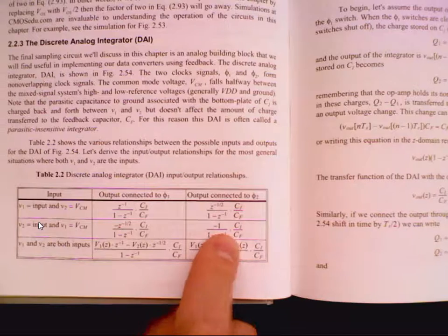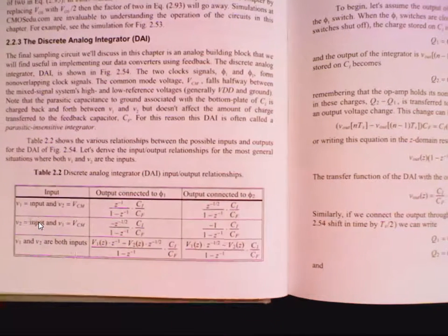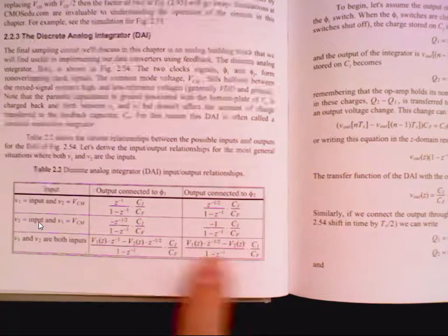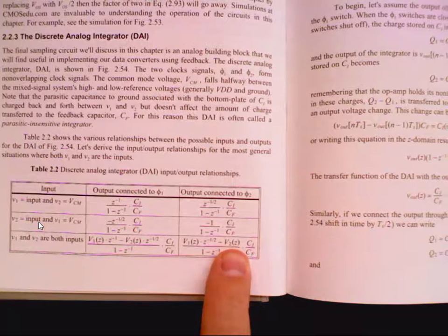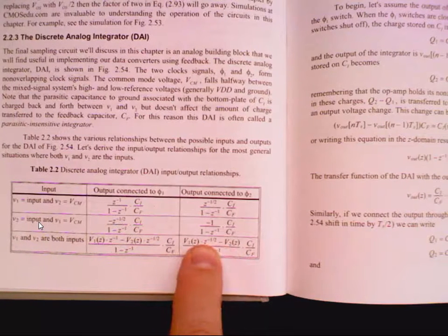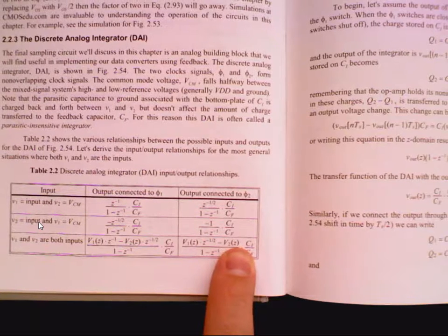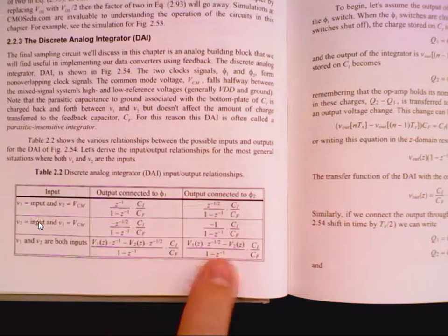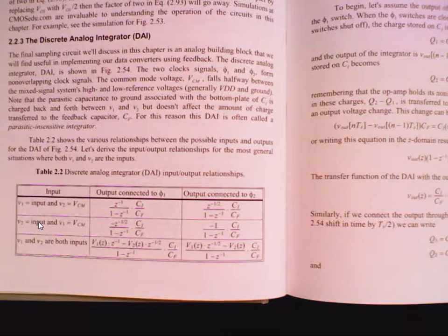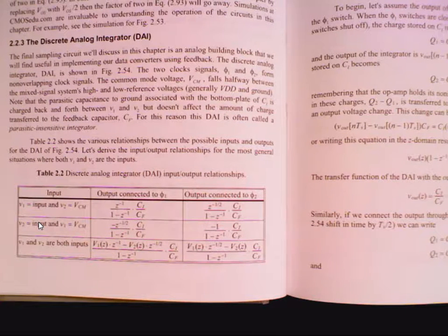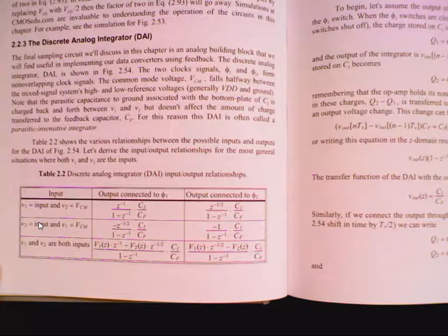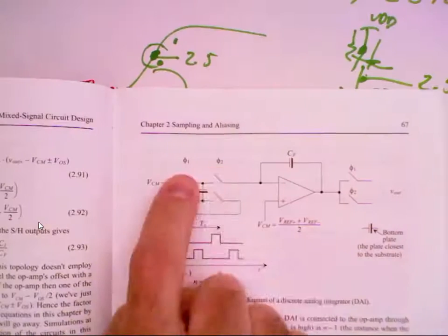I'm not understanding. When you're taking the delta between the input and the fed back output, if you look here in the more generic case, it'd be V in minus V out, right? And then you add that clock cycle delay so that this is delayed a half clock cycle and this one's delayed a whole clock cycle. So that's how you get the delta in the block diagram, V in minus V out. And then the sigma is the integration. No, I think all you do is put this as phi2 and this as phi1.